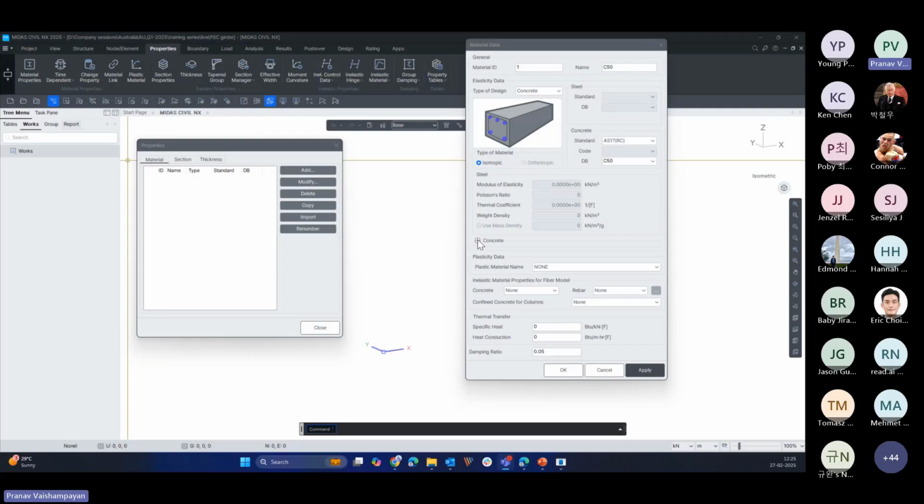Even after minimizing the concrete option, if you cannot view the OK and apply options, then I would recommend you change your system scale to 100%. You can just go on the desktop, right click, display options, and there is a scaling option. You can change the scaling to 100%.